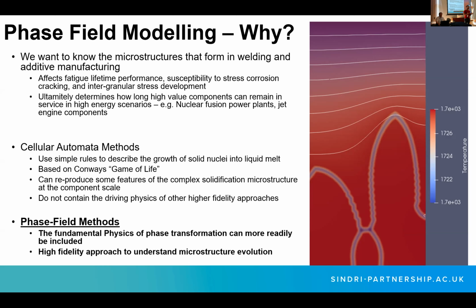So phase field models can be applied to a variety of different processes like fracture or interface dynamics. Anything where you've got a moving interface and a boundary, you basically take the interface and give it a width to give it a volume. So then when you look at the integral of the free energy functional, you then have it described as a volume. So a really powerful technique. So yeah, next slide, please.